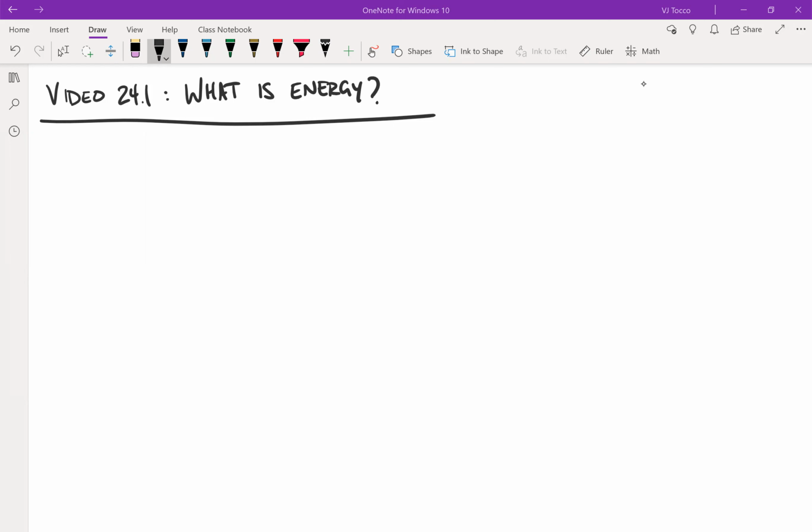Let's start with that thing that I just mentioned, that we know already that energy cannot be created nor destroyed. What does this mean for our purposes? If you've picked up on my hints, we're going to start doing energy balances. And just like a material balance, the general form of any type of balance is in plus generation minus output minus consumption equals accumulation. If energy cannot be created nor destroyed, this means that generation is equal to consumption, which is equal to 0 for energy. So already our energy balance is going to be simplified.